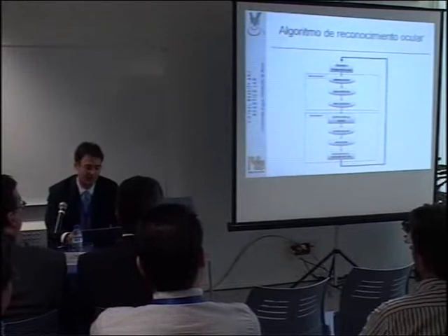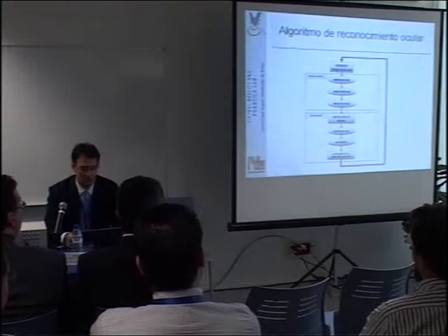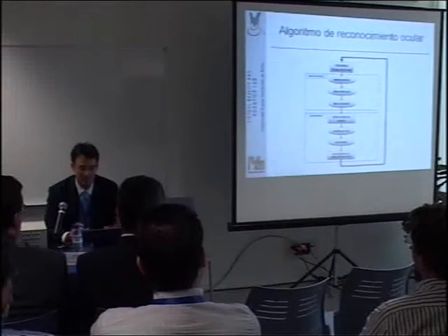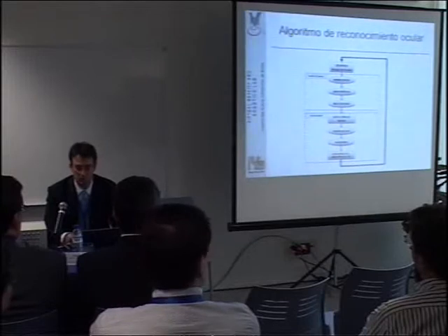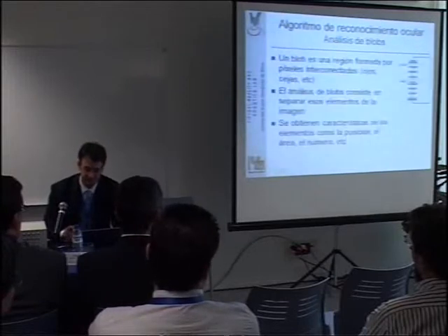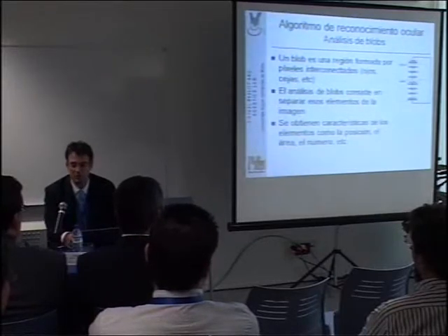Now, the eye tracking algorithm is made up of the following stages. First, the user. We capture the user's image through a camera, but there's a pre-processing stage. And on the basis of that stage, we intend to locate the center of the eye. We compare that through a reference, and we determine the side, or exactly the direction, the eye is taking.